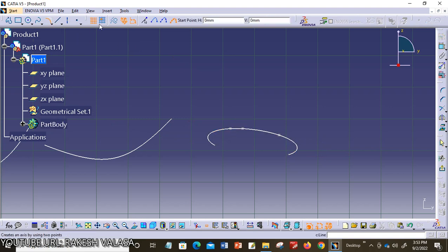Let us move to the second one. I am choosing the second one, 2 points. If you have any doubts, you can follow the instructions given by the status bar. Select a point or click to locate the first endpoint. Next, select a point or click to locate the tangent at the first endpoint. Next, you can draw the tangent line. Next, select a point or click to locate the second endpoint.